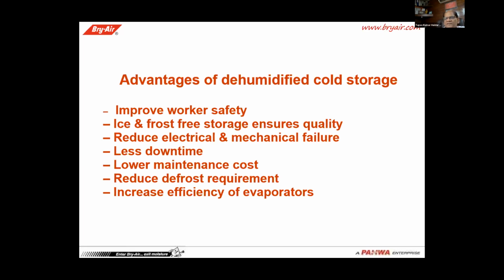All of us know ice is a good insulator. What is happening when there is ice on the evaporator coil? It will not perform at its rated efficiency.